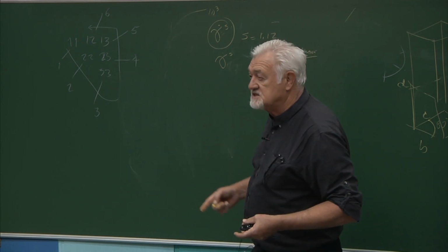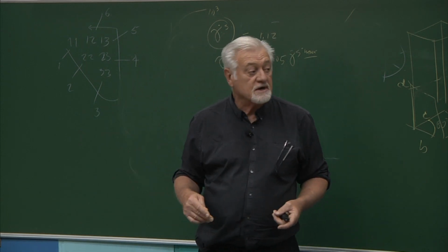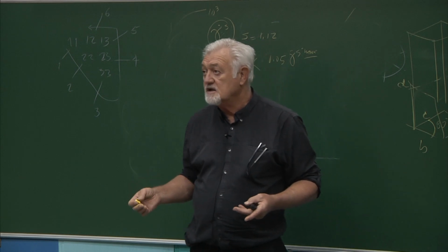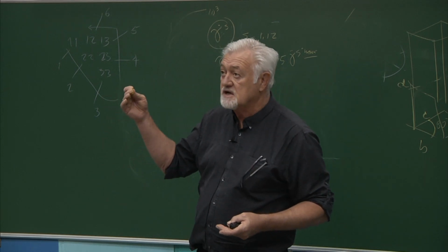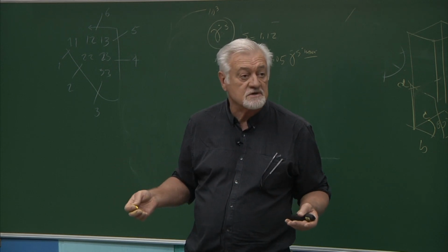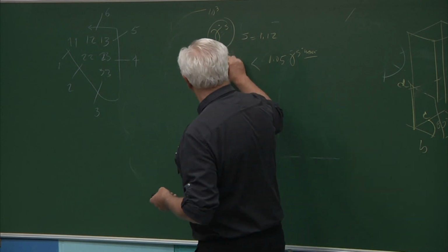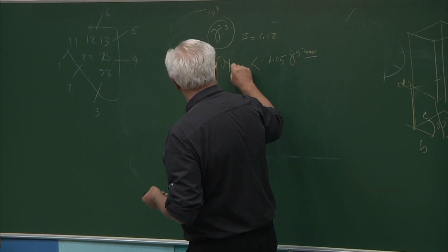This is just a line in one subroutine. If you want to change it, you can change it, but that is the criterion. Anything that contributes less than 5% of the shear of the maximum system is not counted as active. And then that gives you a number, the number of active systems in the grain.